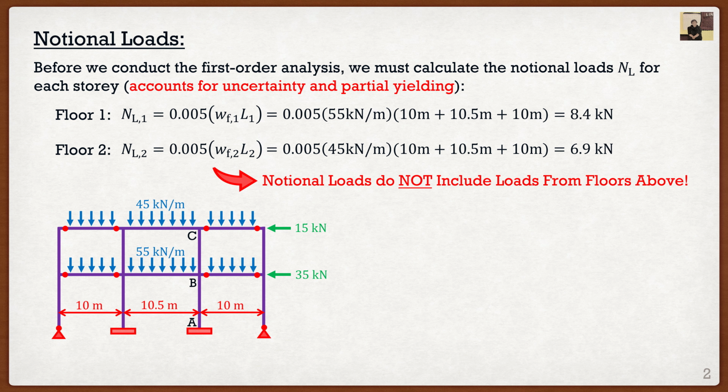Well, as we're going to see in a lot of our calculations towards the end of the example, when we're calculating these loads subjected to stories, if we have a first floor story, we actually have to account for all the loads coming from above. But again, that's going to be in our calculations later. For right now, we do not consider that. If I'm calculating a notional load, it's only going to be the load on that story, nothing above.